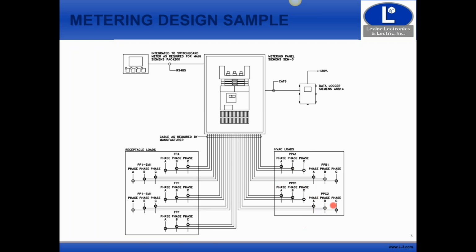Again, as we remember back to our requirement, you can have up to 10% of other loads on these panels and it still be considered HVAC loads. Receptacles are on this side; what this one is not showing is lighting panels. From a design standpoint, that's still a great way to go. If you can separate the loads out per panel, that makes the monitoring a lot more cost effective when we get to the monitoring side.